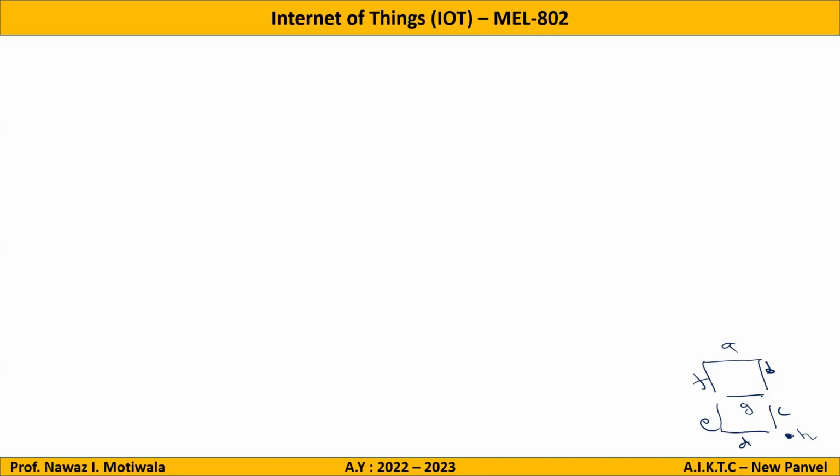So I am starting by assigning int A equal to 13. I am connecting pin A to 13, pin B to 12, pin C to 11, D to 10, E to 9, F to 8, G to 7, and H to 6. It's a random assignment. You can choose any pin from 2 to 13. But when you assign in sequence like this, it is very easy for us to do the programming. We don't have to remember the things. So this is the first step.